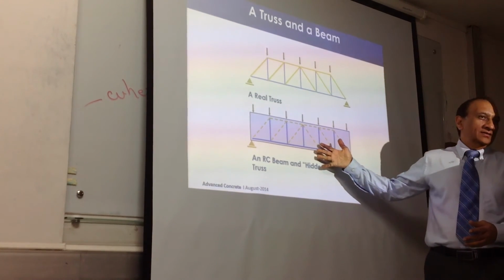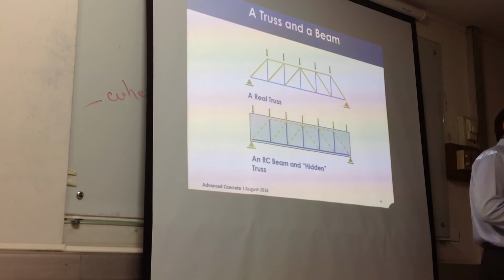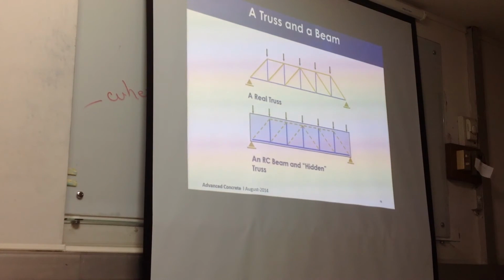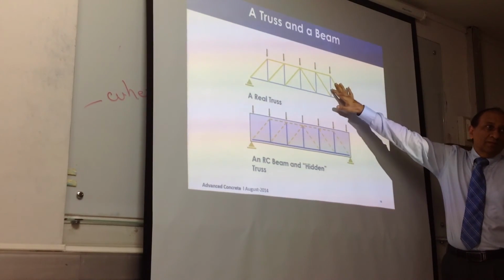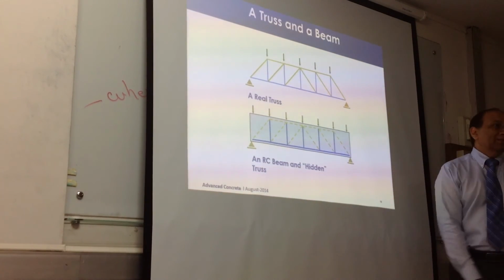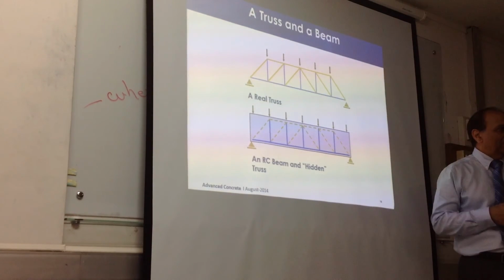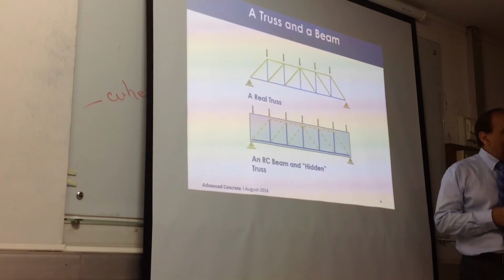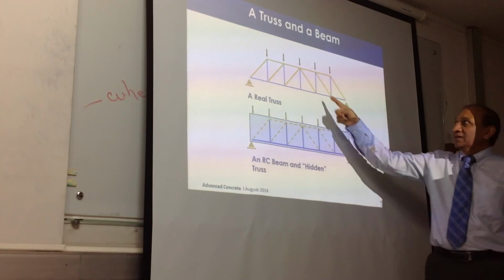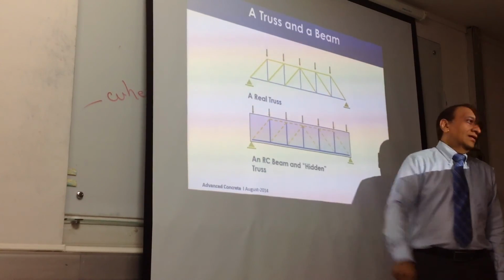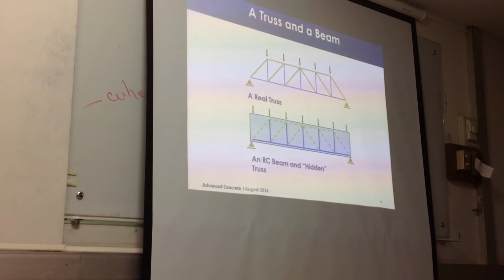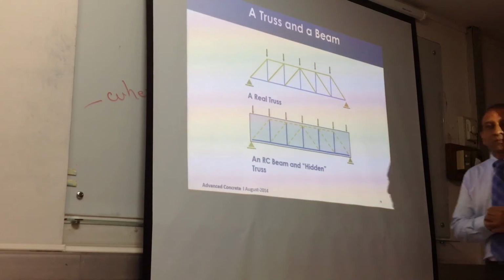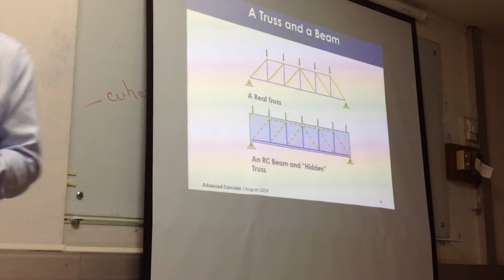Same thing in concrete. So we can completely get rid of the shear thing and only deal with axial compression and tension, which we know how to deal with very well. Correct? So we will jump from here to here and then forget about the whole beam, this whole complication that we have been talking about. Only based on one assumption: that concrete does not exist where it has low compression. If there is a tension, concrete takes zero tension. If we make that assumption, our life will become very easy, and we will see that later.